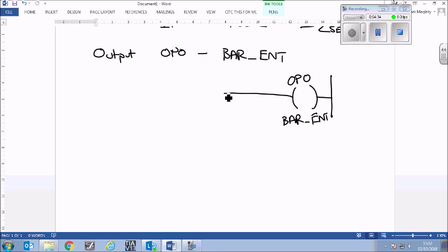So from the text that we have here, and I'll get you handouts of them before you leave, it says the entrance of the car park's left hand side. That's fine. When the car arrives at the entrance of the car park, operates the inductive sensor IP6 on the ground. When the ticket button's pressed, IP0. It operates the barrier after a 2-second delay. So what I'm going to do is show you 4 images here of the different stages at which the car can be at.